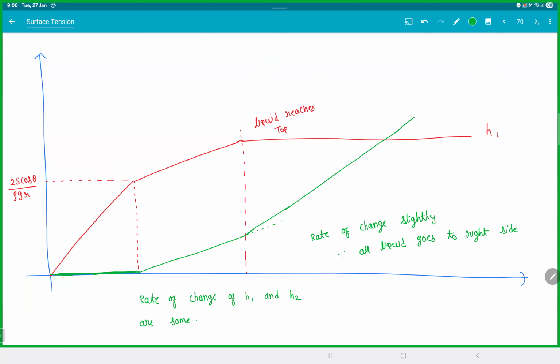increasing, increasing, and then this becomes constant. So this h2 will actually exceed h1. This is the point where the liquid starts leaking. Straight line, but liquid starts leaking. Again, if you look here, the rate will start decreasing. The rate of change of height will decrease because the liquid is shared by both of them now. Again, all are straight lines, no curves, but the slopes will keep changing a bit.